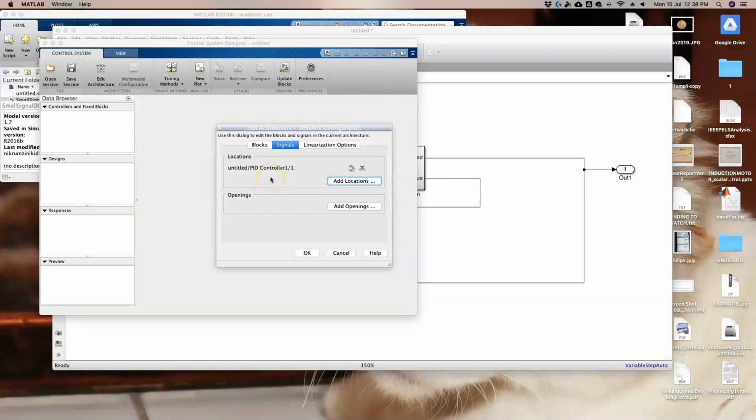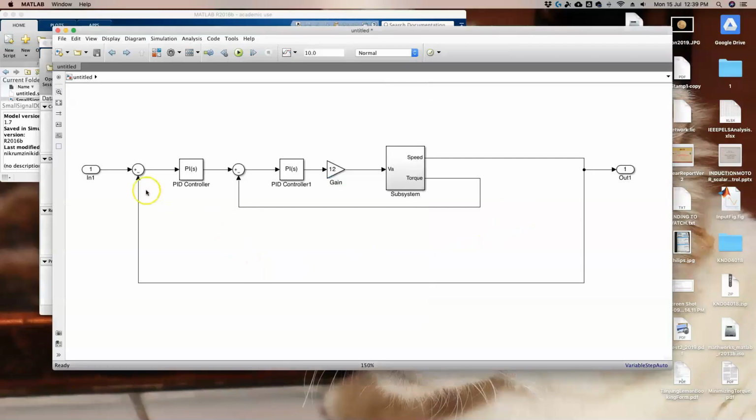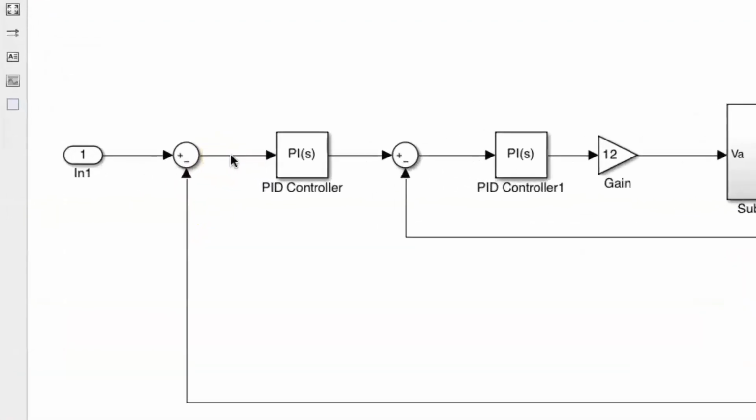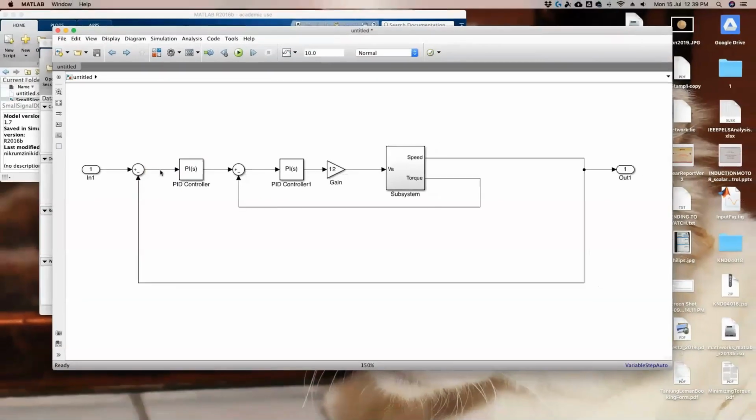Okay, since we are designing the torque controller for the torque loop, then we need to open the speed loop. So this is where you define the openings of the loop. You look at this Simulink block here. What we will do is we first open that speed loop. So I will define that as the opening, and I will only be left with the torque loop here.